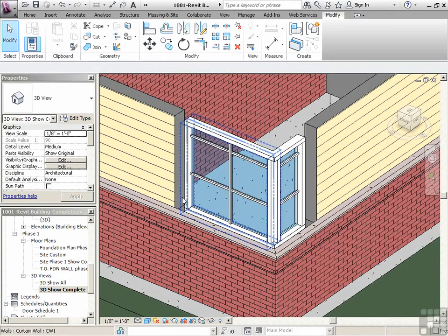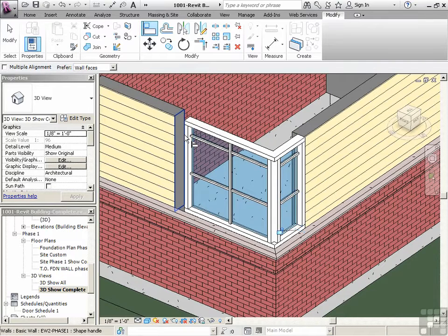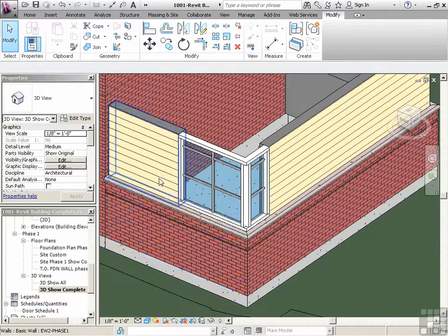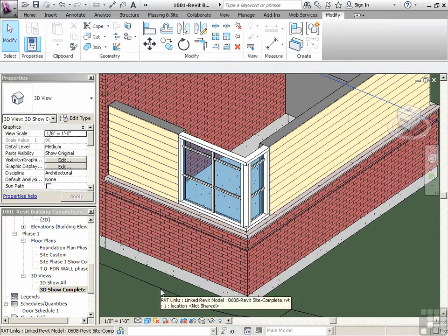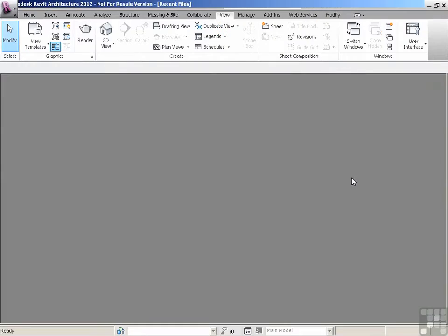These curtain walls can be standalone. Now, if I just use the align tool, I can pick this back face and just align the end of the wall to it. Okay, just like that. Good, so that's a start, a little bit of a best practice on dealing with corners. We will look at this mullion as well in future lessons. Okay, good, so let's save that much and then shut that down.